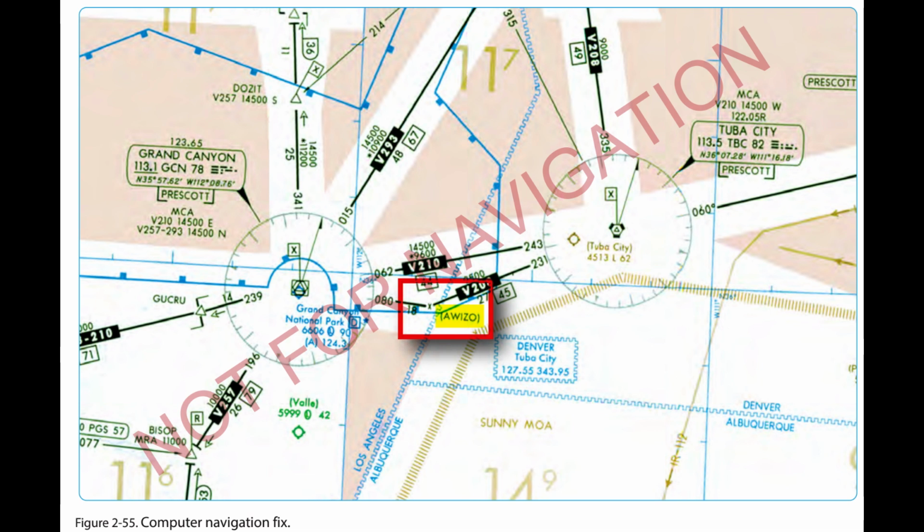This onboard performance monitoring and alerting capability, therefore, allows a lessened reliance on ATC intervention via radar monitoring, automatic dependent surveillance broadcast, ADS-B, multilateration, communications, and/or route separation to achieve the overall safety of the operation.